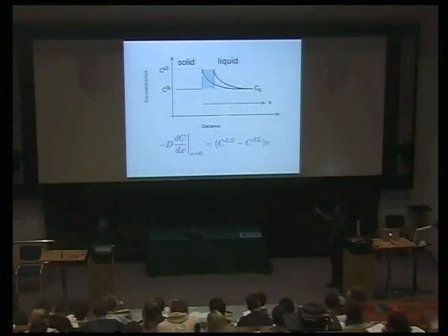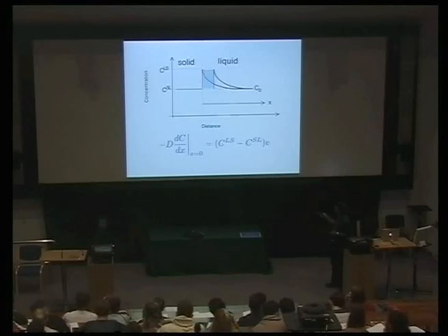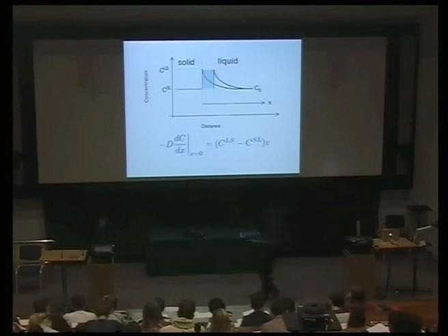When the profile moves from this point to this point, I've displaced that much solute. I've exaggerated the distance between these two. If I make it very small, then you see that it's the difference between the concentration here, multiplied by the velocity. Okay? That's the rate at which solute is being pushed ahead of the interface.